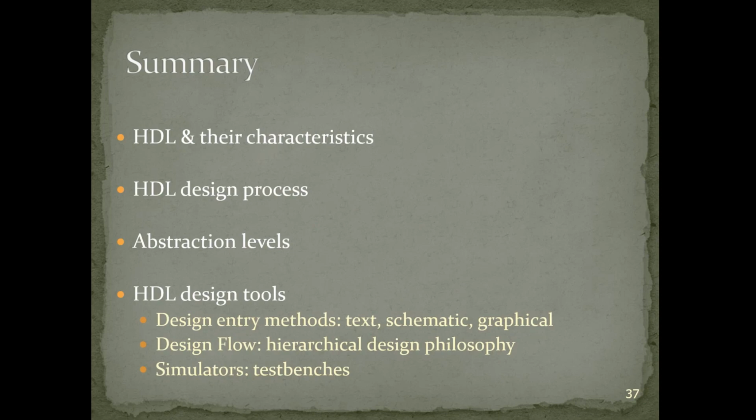Also gave you a good flavor of how the design process is meant to look like, what the various abstraction levels at which we can design are, and a bit of a flavor into what the various forms of inputs and outputs are, and a bit about the process that a hardware description language tool tends to follow. From text entry to graphical and schematic, to simulation and to synthesis.